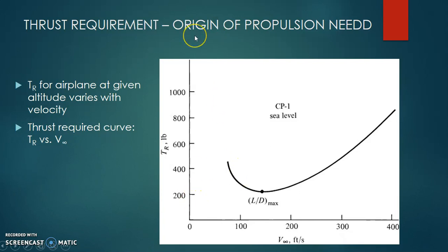At zero velocity, of course, you would say it means maximum, as we discussed, because you have to first start the engine and take off. The moment you reach a point where L by D is optimized, this is the best gliding curve also, if you remember. So as L by D, the best optimum gliding trajectory, is reached, that means aerodynamically you have extracted your performance to an optimum, and required thrust is at its minimum. What happens then? As velocity increases, even though lift is increasing, you don't need that much lift because your weight is not so much required to be balanced.